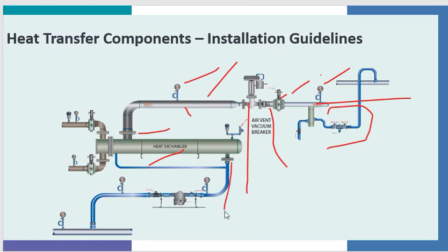The next thing is condensation coming out, and the condensate is coming down here to the steam trap. But one other thing, up here, the heat transfer needs a vacuum breaker air vent. Air vent to vent the air at startup out of the process.